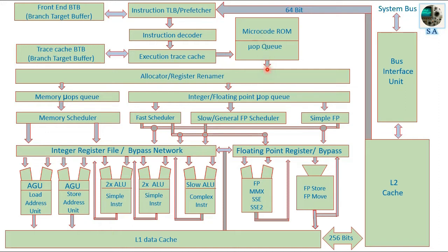Here we have what's called the out of order execution engine, where the instructions are prepared for execution. This part of the machine will reorder instructions differently to allow them to execute as quickly as their input operands are ready.